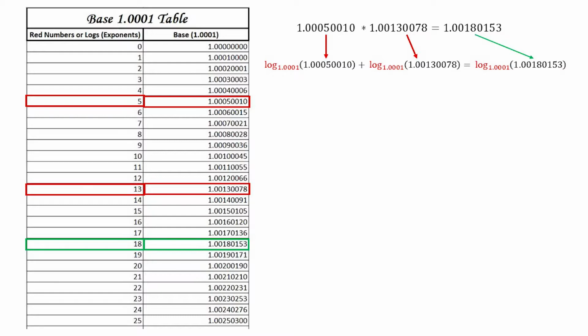Say I have a plus 2 dBu signal, and I'm at half the power now through a pad or something, or let's say a plus 20 dB of a gain structure. All I do is I just add 20 dB to that. So plus 2 dBu through 20 dB of gain, I'm at 22 dBu now. It's pretty simple. You don't have to divide by 2 if you're halving the power or whatever, or halving the voltage, you go down 6 dB. So it just makes it easier.